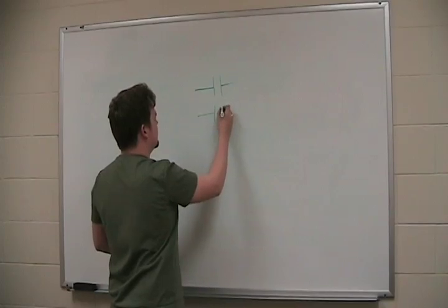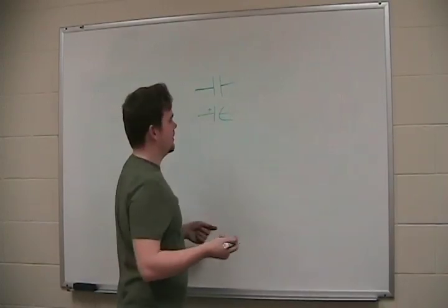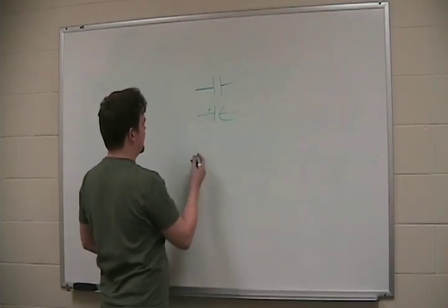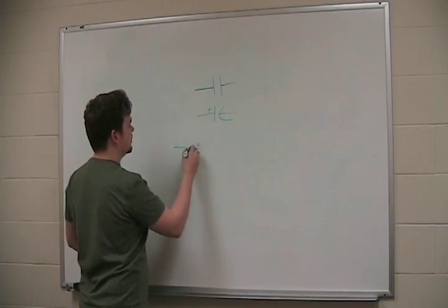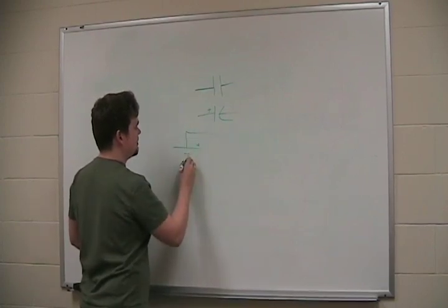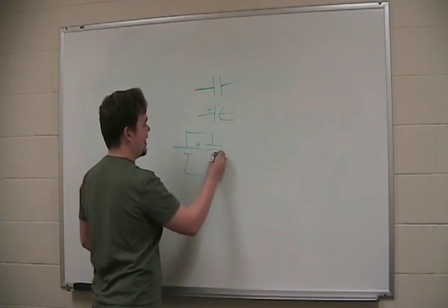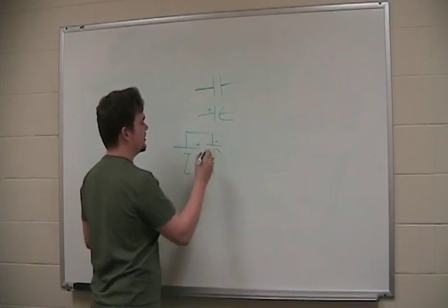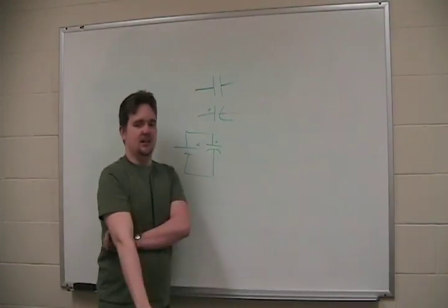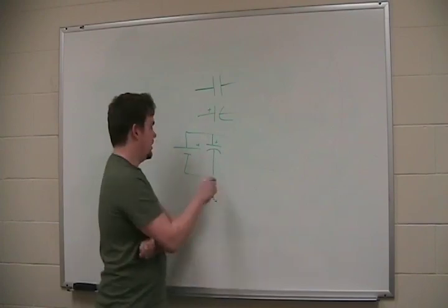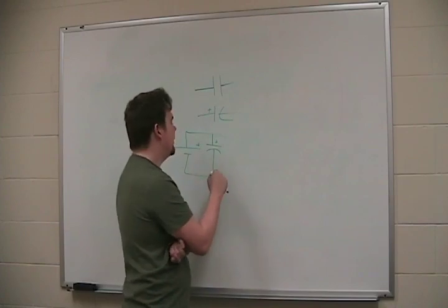Here is an electrolytic, or polarized, capacitor. That means if I was to put it in a circuit like this, I would have to put it in so the positive is facing the positive line of the voltage. If I put it in backwards, I could damage the capacitor or even blow it up, depending on how much power there is at the power supply. Not a good idea. Always make sure you put it in the right way.